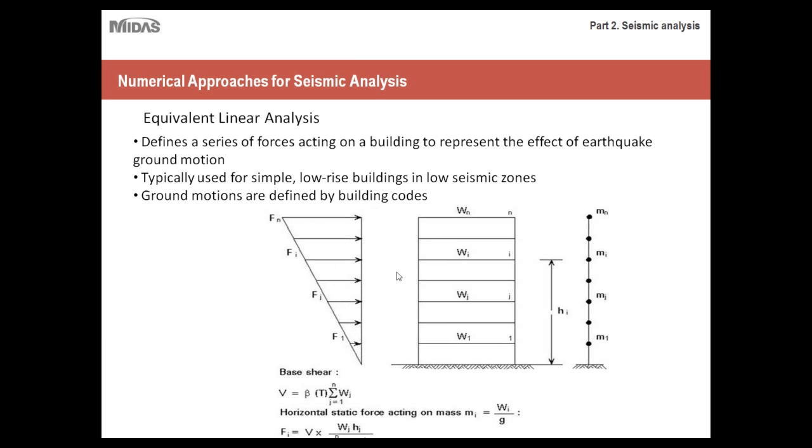So for example, here you have, I don't know how many stories this is, but you have a low-rise building, and in order to create your seismic loading, you just take a force and model it as a triangular distributed load, which increases the higher you go up, because the farther away you get from your foundation, the more flexure you'll experience as you go higher up. But obviously you're making several very large assumptions when you're doing this type of analysis.